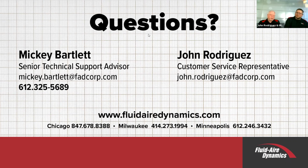And the other thing about too small a compressor room, boy, they heat up in a hurry. I've been in compressor rooms where you walk in and it's 120 degrees to start with. It baffles me that people wonder why they have moisture downstream, or why the compressor's overheating and shutting down, when the compressor room is that hot. The end result is, as I said, a 15-degree approach. If you've got a 120-degree room, you've got 135-degree air temperature going out. A dryer of equal size can't handle that additional load.